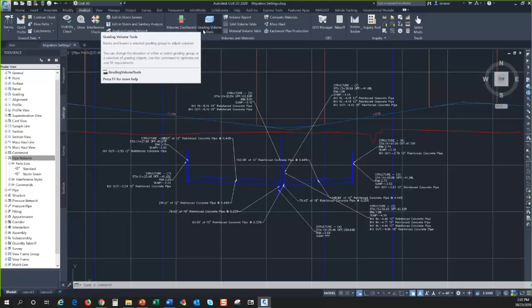So that calculation adjusts the TC, but the travel time in the pipes is calculated. The TCs I was inputting, those were the TCs I calculated in my case using the FAA method, and that's the TC of the drainage area from the most distant points to that inlet. I hope that answers your question.